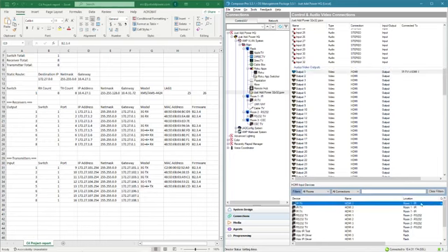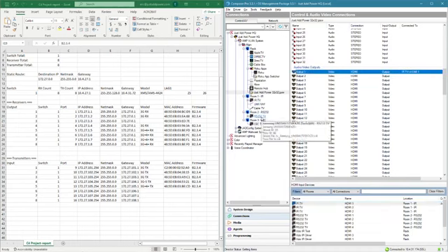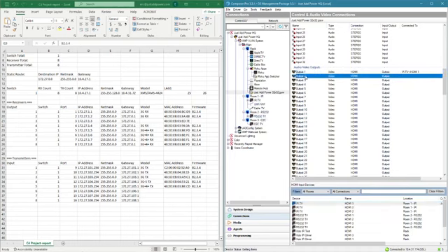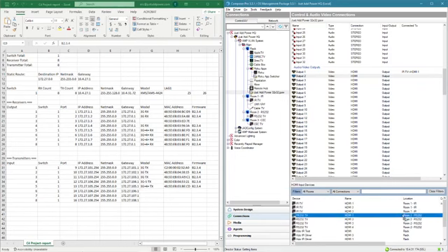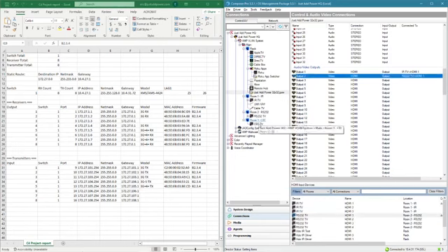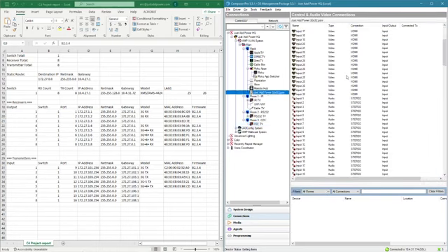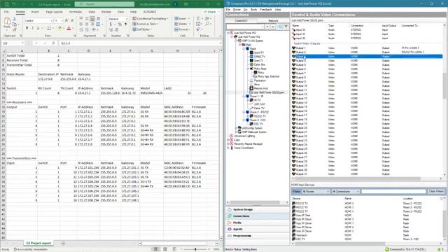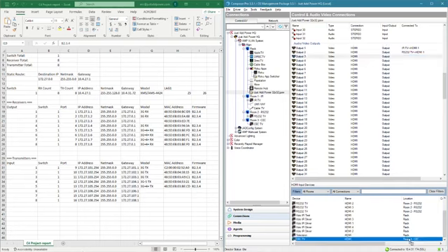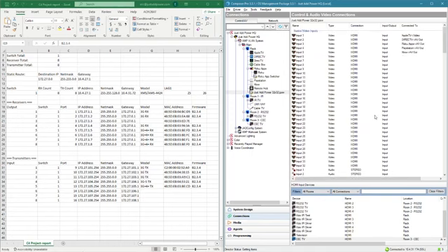Drag that down. Display 2 is our room 2 RS-232 TV, HDMI 1. And we've got room 3, our CEC TV. Whoops. There we go. Scroll back down. Output 3 to our CEC TV. There it is. So we've connected our inputs and our outputs according to our report file. At this point, switching works. Our driver is fully configured.